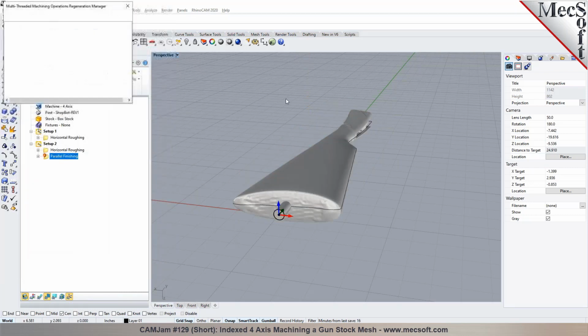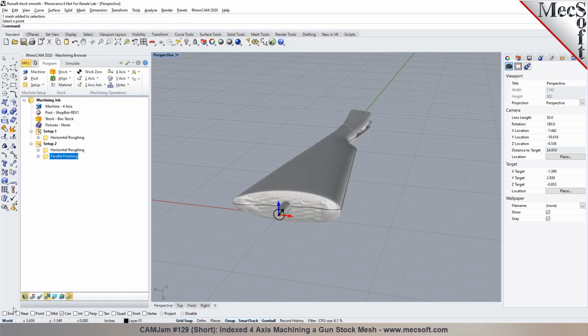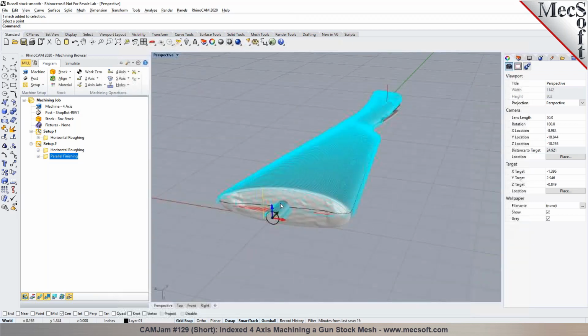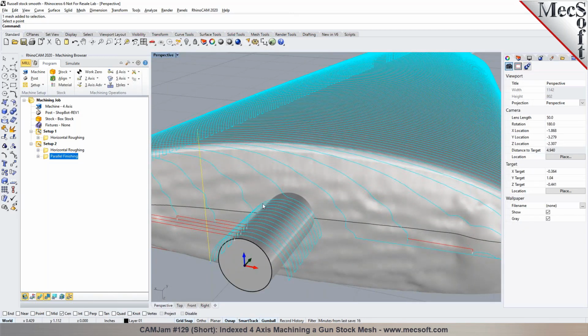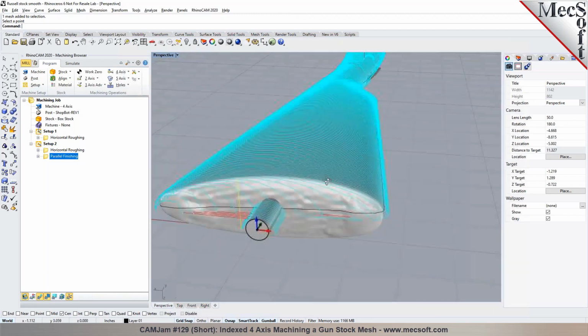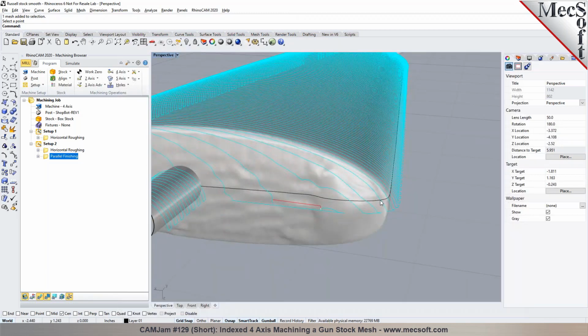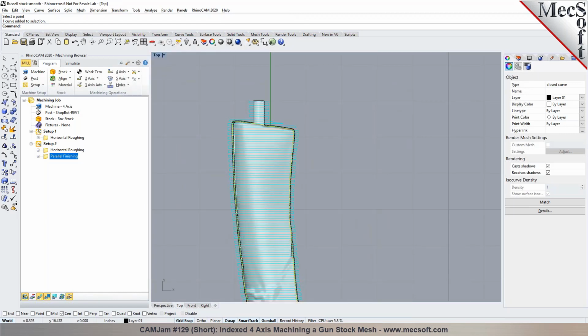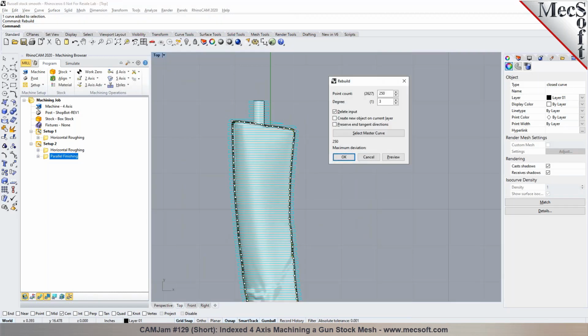And now I'll pick generate. So the system will automatically compute the toolpath based off the part geometry. All the finishing operations use the part information that you have right there. So you can see it's also going in and cleaning up these areas as well, right? So if you wanted to not cut into those areas, that's where the containment comes into play. So you could use a containment boundary in here to create a little area to limit your toolpaths.